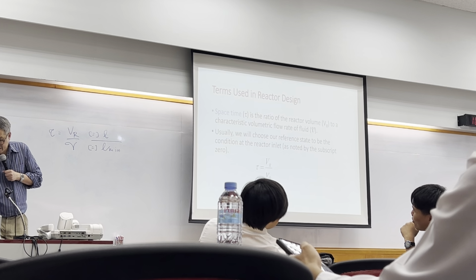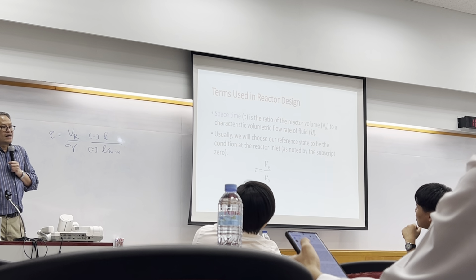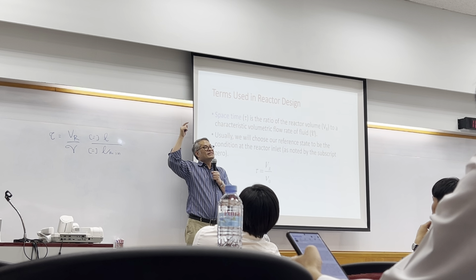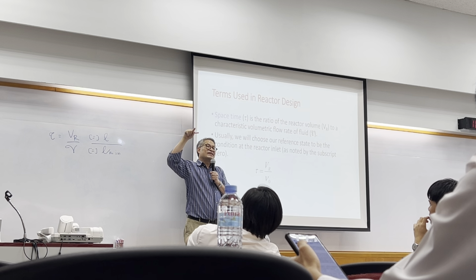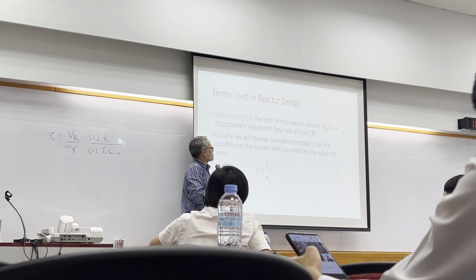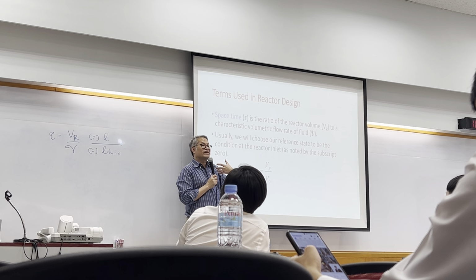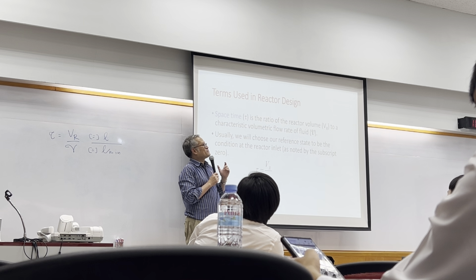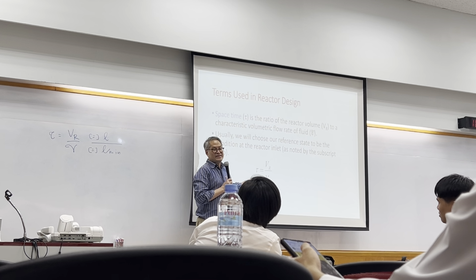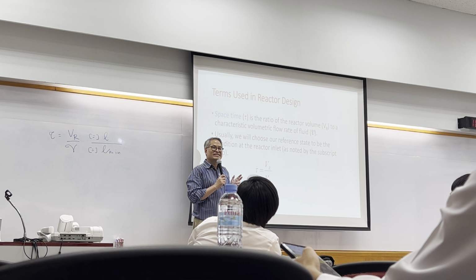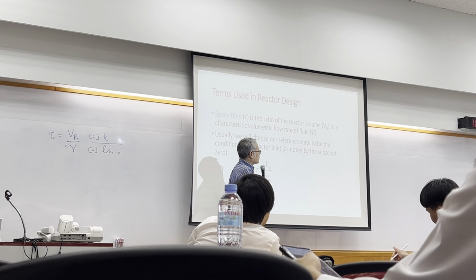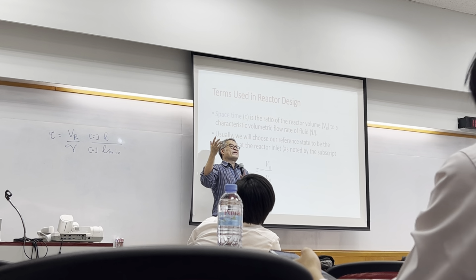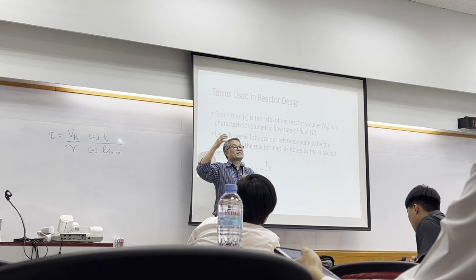Any question? Residence time is the time that the content spends inside the reactor, right? But residence time or holding time is sometimes a little bit different. It could be similar. Space-time makes it ideal. But with residence time, sometimes some reactant stays a little bit longer because it doesn't get mixed properly.